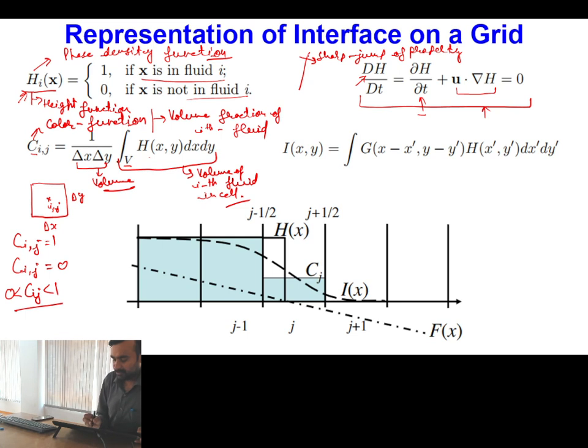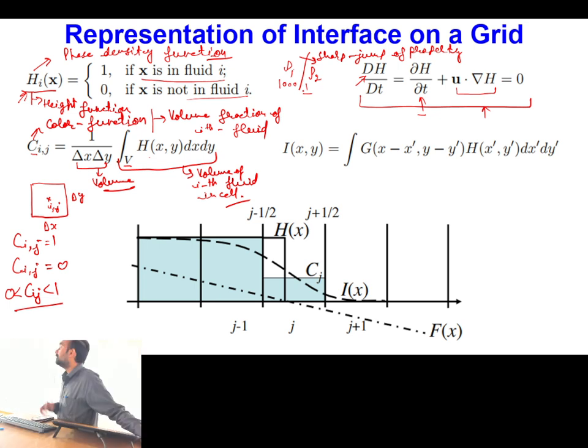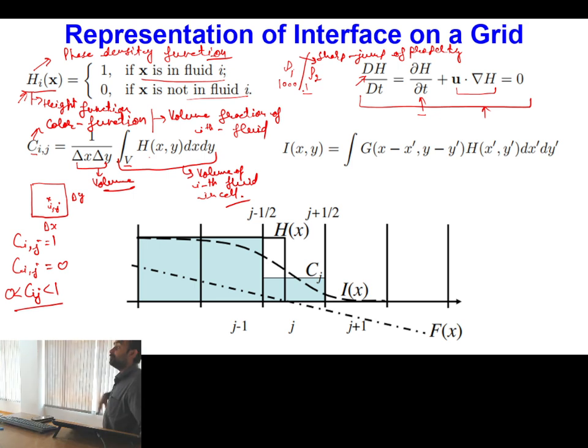In this portion of the height function, density is say rho1, and whenever I go to the other side of the interface, immediately density becomes rho2. If I have water and air, then on this side I have density 1000 and on this side density 1, so the density ratio all of a sudden becomes 1000. Likewise, the viscosity ratio for this combination may suddenly become 100.